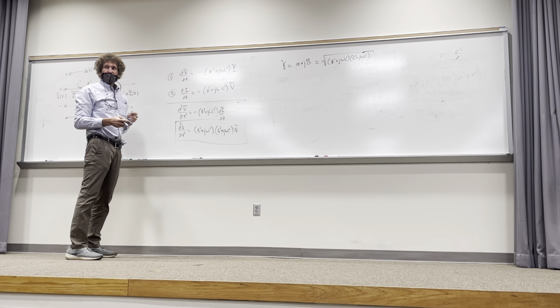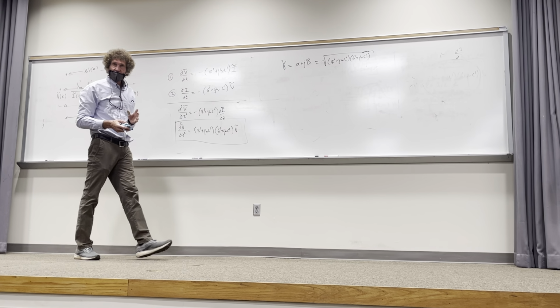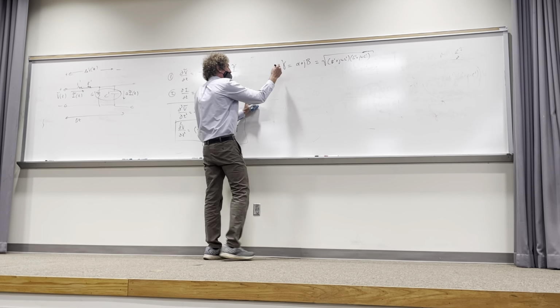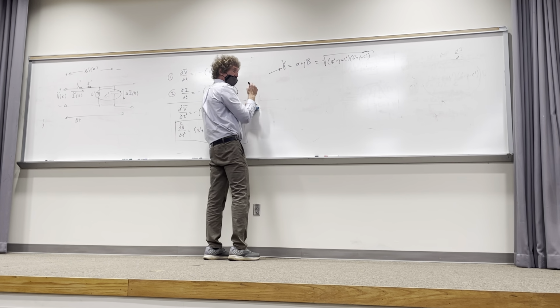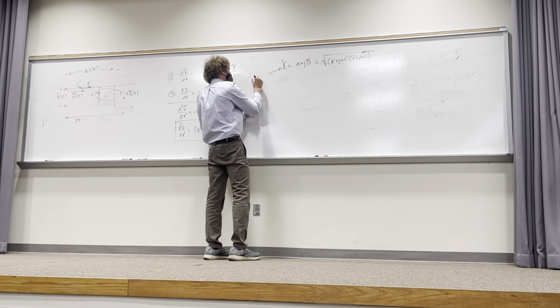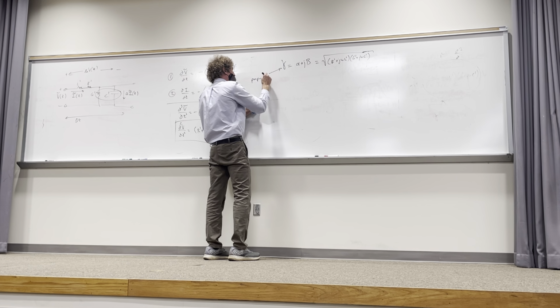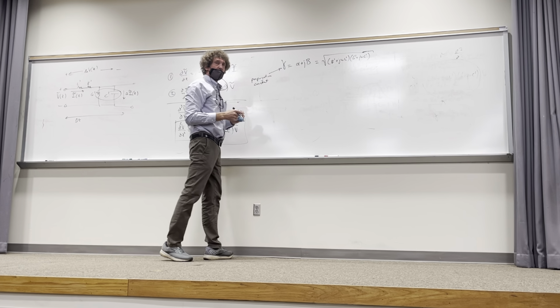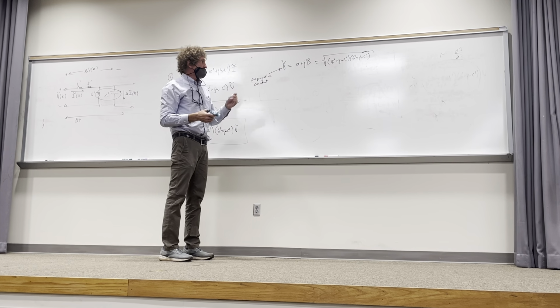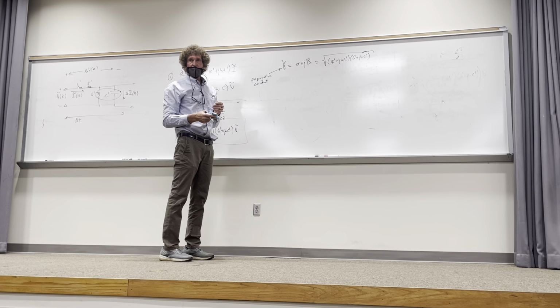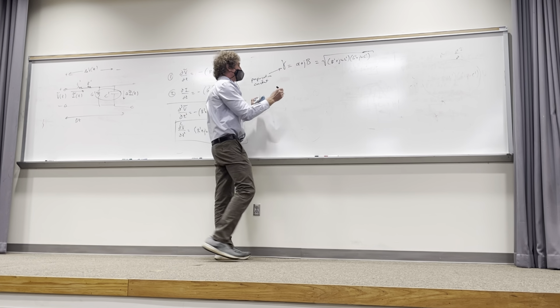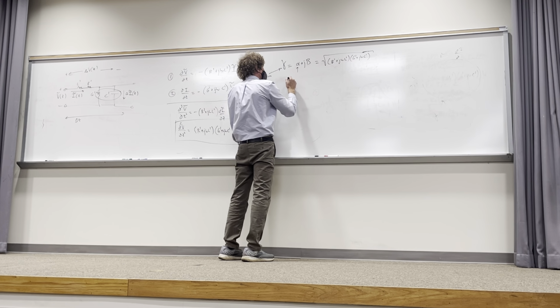Now gamma, does anybody know what the term, these are common in physics and in mathematics. This is usually termed the propagation constant. The propagation constant is alpha plus j beta, so they have to have technically the same units. Alpha is called the attenuation constant.